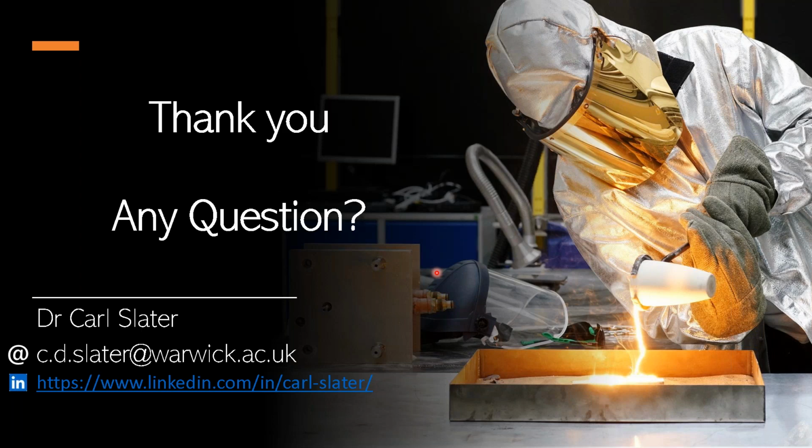I think the failed test that you showed was actually pretty interesting, and that may have spurred this question. It says, question about near solidus forming. What type of lubricant should be used at the die and workpiece interface? Is there a sticking problem between the workpiece and the die? Our team typically uses graphite foil with a nickel-based barrier. Do you do this as well, or have you experimented with other methods?